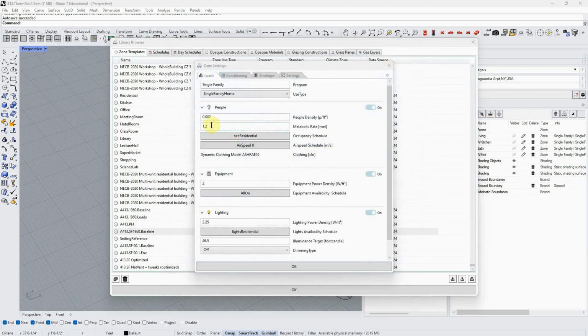So that means their heat from this metabolic rate. Remember, we're little heaters constantly putting out heat as we metabolize food. This is defining when the people, those heat sources, will be in the building. I set equipment and lighting power densities that were pretty high because, for example, this would be based on incandescent lights rather than LEDs. I didn't have any dimming.